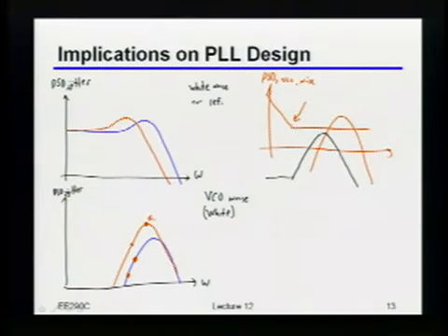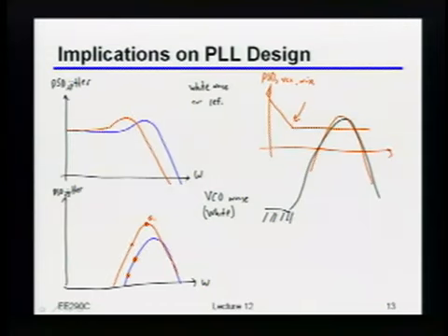And then just look like the bandpass filter, right? So let me just line everything up. Okay, yeah, you're right. Right? Does that make sense? So you're right that it's not that it has no effect. It has some finite effect due to the ratio of the loop bandwidth with that 1/f corner.